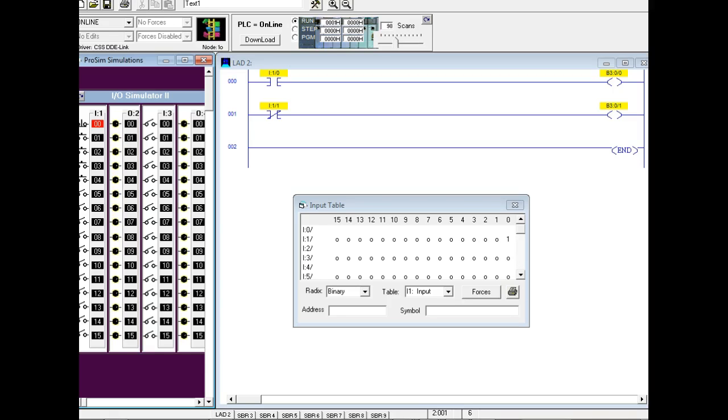Relay contacts are not the problem because we don't hook up relay contacts to an input, right? So if I'm using all normally open push buttons, then I have to use examine close for every input. And then you use a normally closed switch, because that means it's true and it's going to do whatever it's supposed to do.